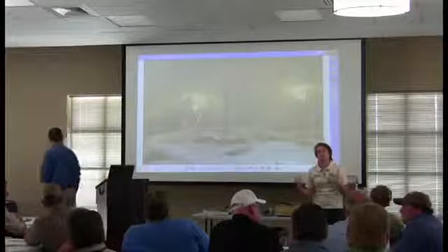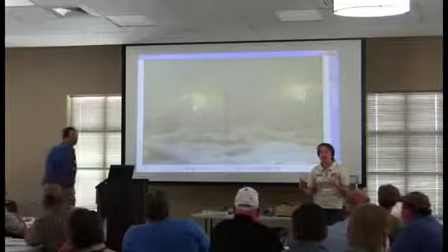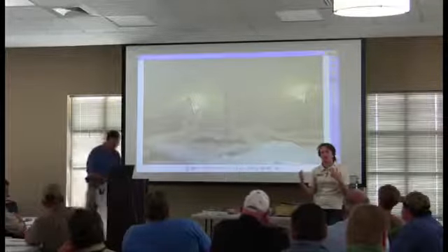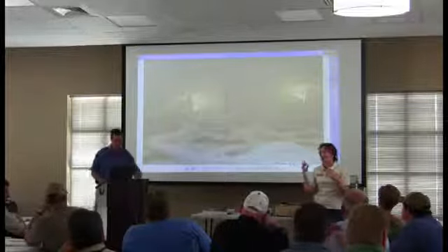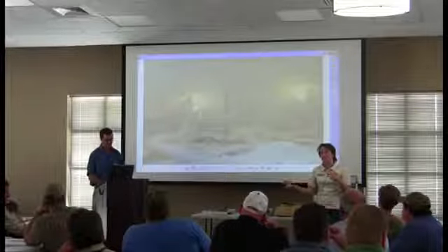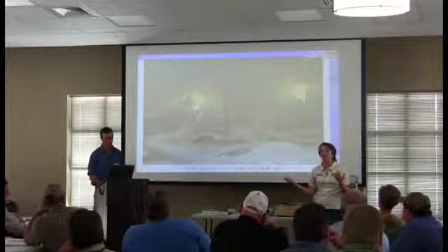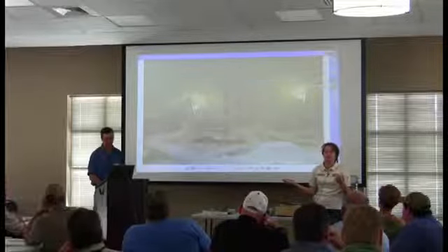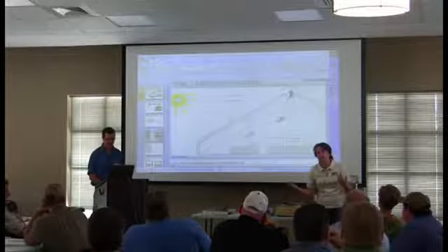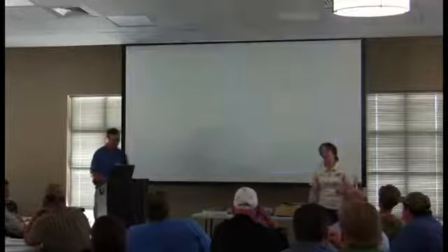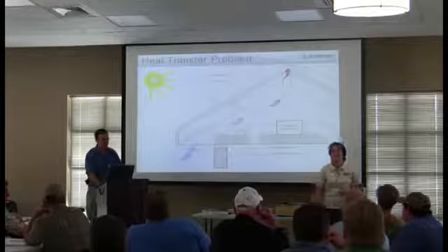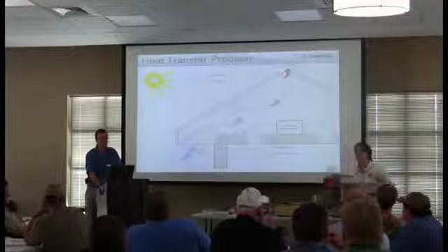If you bring your ducts inside conditioned space, it's not directly the payback for the insulation, how well the house is going to perform, but when you actually bring the ducts inside conditioned space by using this application, you might be able to go a whole half ton or a ton less on your actual heating and cooling equipment. I mean, that's the best thing for me. Also, you might be able to skip the duct blaster test. There's some additional savings, right?